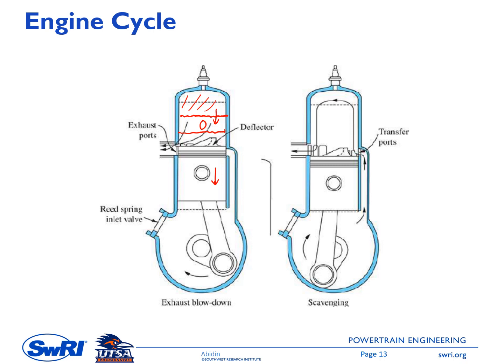The one on the left side is called the exhaust port, and the one on the right side is usually called the transfer port. Also important here is the difference in height between these two ports. You can see here the exhaust port location is slightly higher than the location of the transfer port.